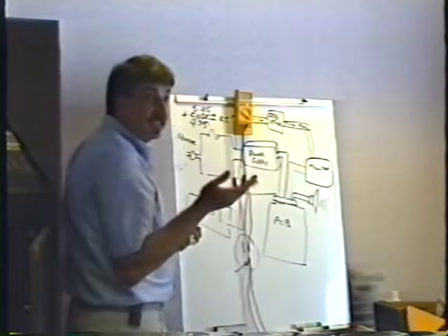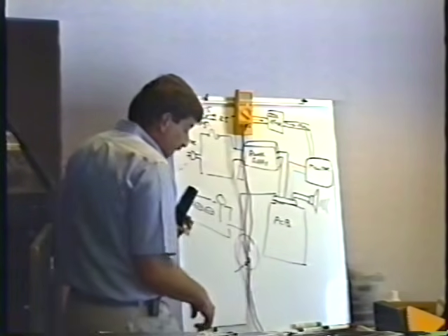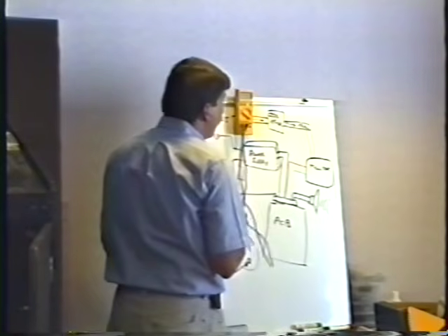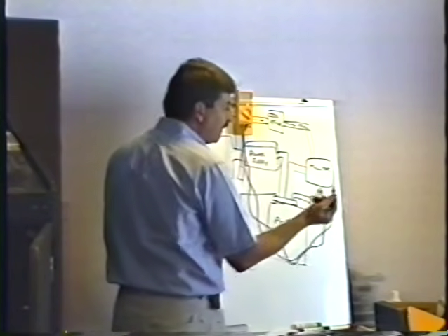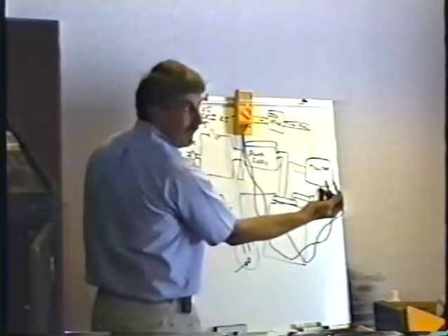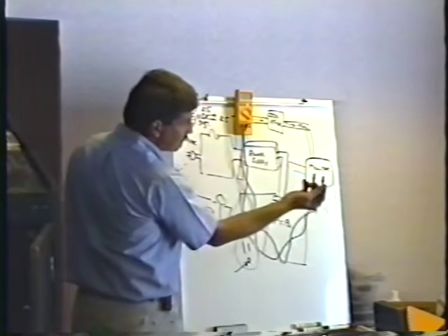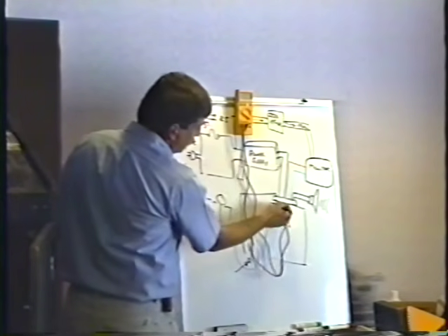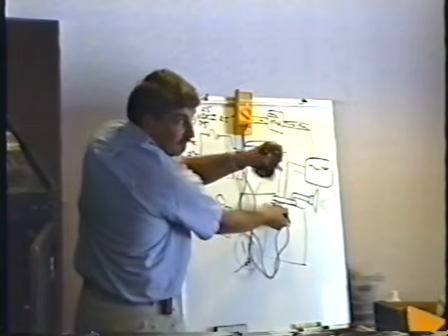Now that kind of takes 3 hands to do. There's a couple of ways around this. Number one, if you really like Chinese food as I do, and you can do this chopstick style, then you can use your meter leads like chopsticks and just go like this. Then you've got one hand free to adjust the power supply voltage.